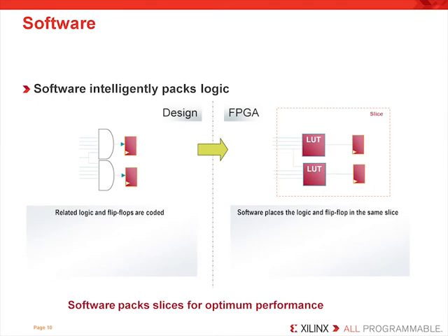The Xilinx implementation tools, commonly called the place and route tools, take the synthesized design and map the logic to the FPGA resources. In this example, that is simply a gate to LUT exchange. So while you will code in HDL with a gate functionality, it is the synthesis tool's job to build a design netlist that includes Xilinx primitives, that is, LUTs and registers and other dedicated resources.